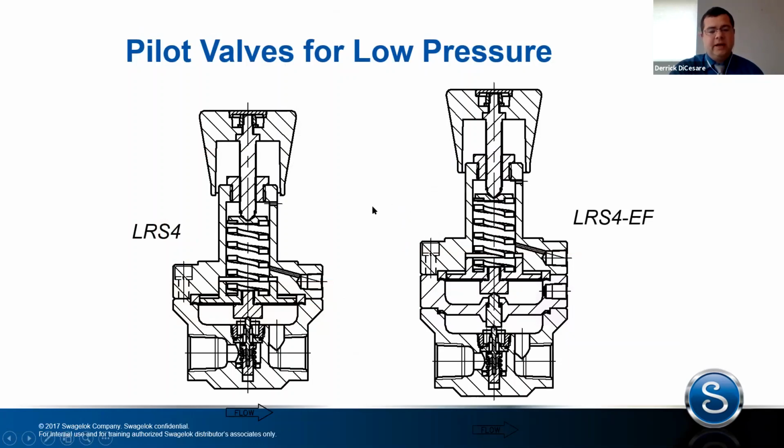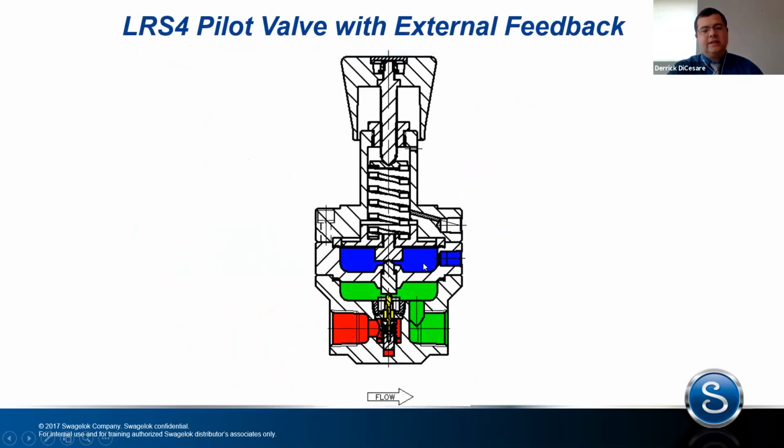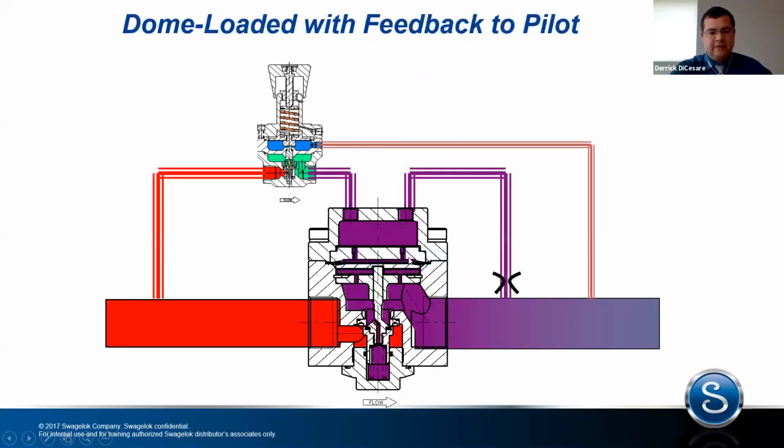The other way is, instead of going back to the regulator itself, you go back to the pilot regulator. So we're seeing another little wedge in here that's going to take that output signal, and instead of going to that, you're going back to the pilot regulator. So now you're making the change on this part, so this is going to be more sensitive and an even better performance than going directly to the regulator. So when we talk good, better, best, this is between better and best.